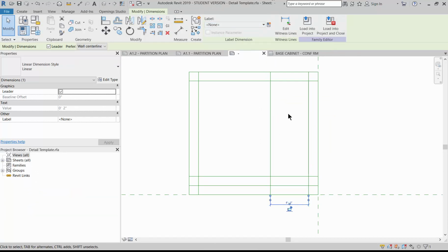And what I did here, instead of having the extra line on the top, because for legends the title is on top, and also for sheet notes, for details we put the title on the bottom when we set it up on sheet. So we need to have an extra border along the bottom, so there is plenty of space to place the title in that 1/2 inch on the bottom, and then 1/2 inch border around.